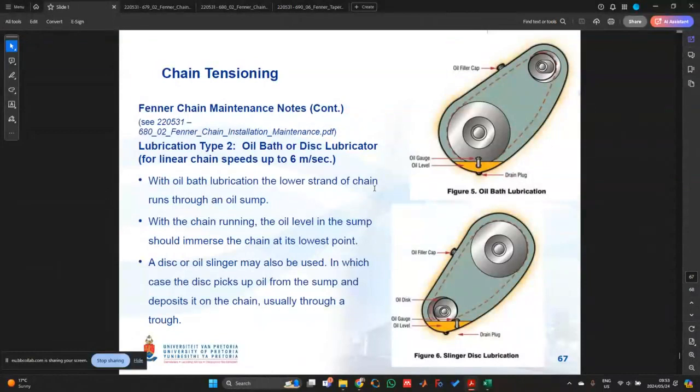Are there any questions with regards to this study theme? Yes. There was a slide that said if you have an odd number of driver sprocket teeth, then you actually want an even number of chain pitches. You'll see in the problems that we looked at, whenever we got the value for the chain length, what we wanted to do was round up to an even number.